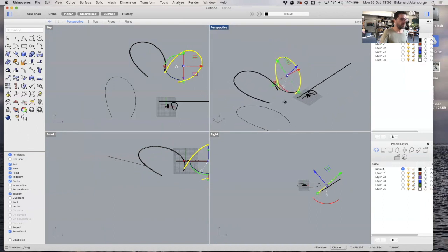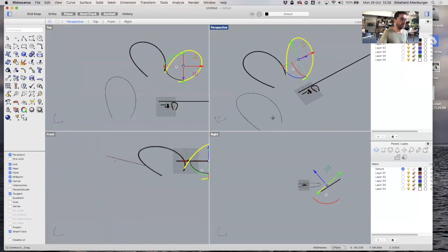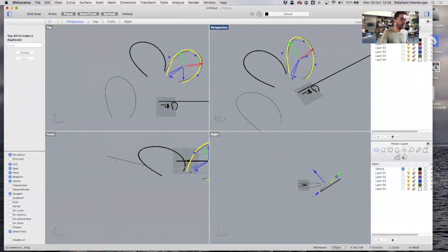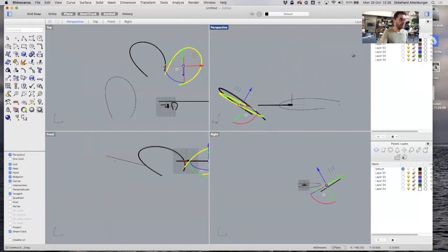Sometimes it's difficult to figure out where they go. Is it this way? No, is it that way? But once you laid them out, you can manipulate them and figure out how they move in space. So please play around with it. Make a few curves. I want to see whether you can figure out how you can use the command extrude and sweep with rail.